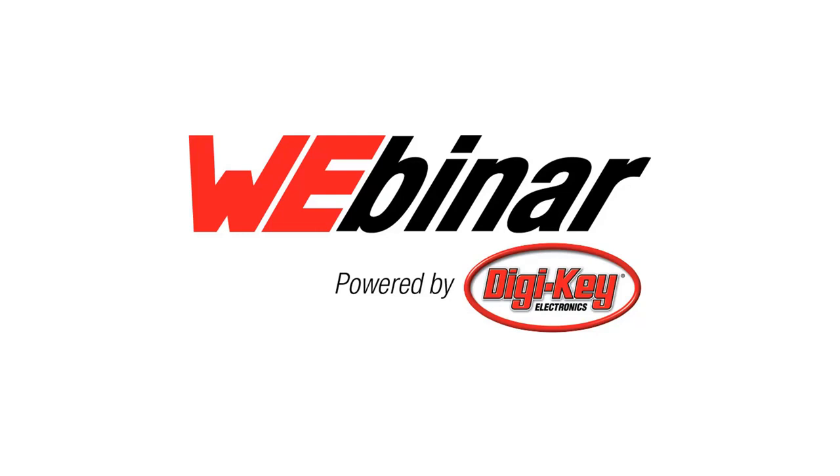So the ST-USB 4500L and the 4500 are both sink devices. ST also has the ST-USB 4710, which is a source-only device that very similarly acts with this auto-run state machine. And then we have the ST-USB 1602, which can do a dual role and can act as either source or sink, although that part does require an external microcontroller. That's a bit more complicated to do the dual role, so we're not able to do that in a fixed state machine.